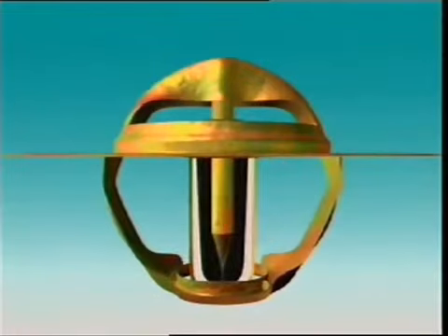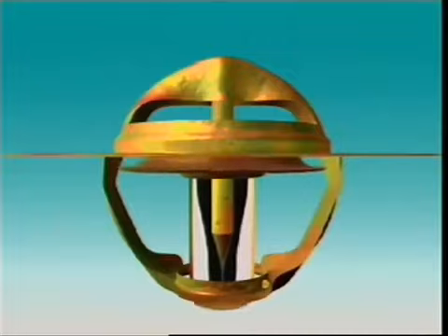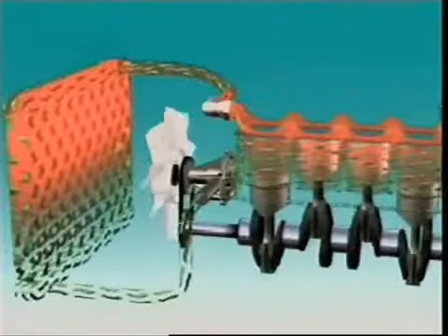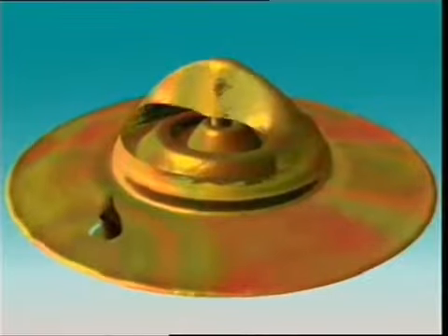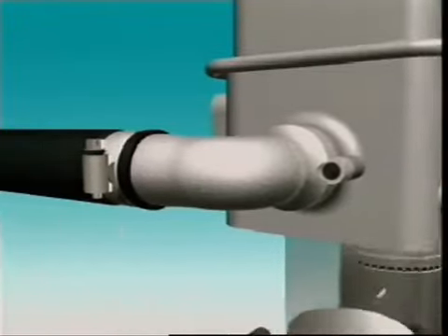As the engine warms up, the coolant in the engine gets hotter and hotter. This thermostat has a wax-like substance that expands as the engine nears its operating temperature. This starts to open the valve. Coolant starts to flow to the radiator. Thermostats have a small hole or valve to let out air that's trapped in the engine block. Heated coolant is pumped from an outlet in the cylinder head. It goes into the upper radiator hose, then to the radiator.